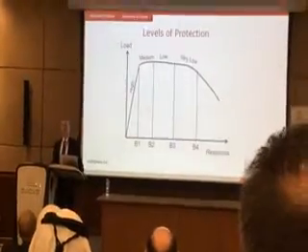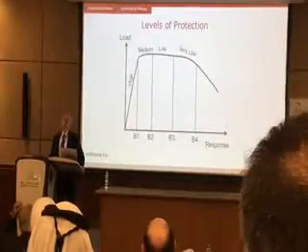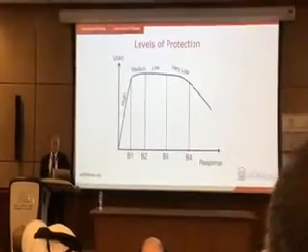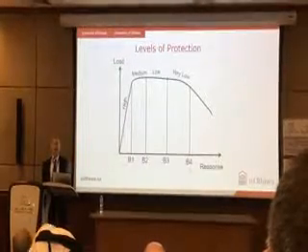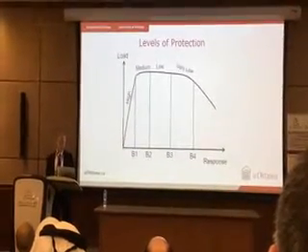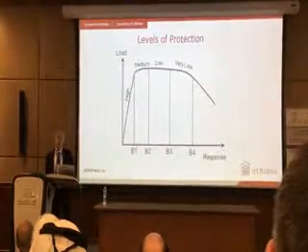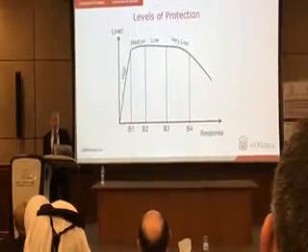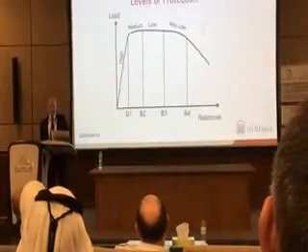Of course, these concepts are vague concepts until we look at force displacement relationships. Again, structural engineers look at numbers. Force displacement relationship, these quantities B1 through B4 are known as response limits. If I have high level of protection, and I just said that my structure has to remain elastic, so I design it for B1 ductility level, and B2 is medium level, which is used for life safety, and then you have low and very low, which is collapse.